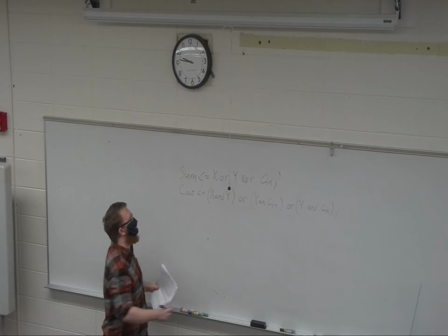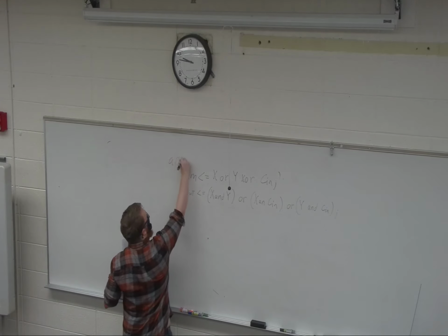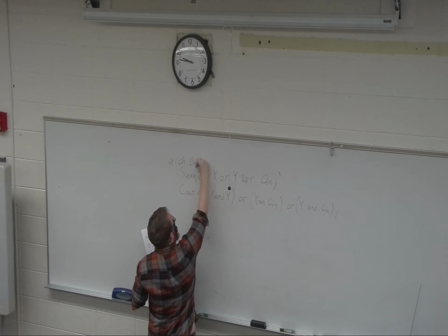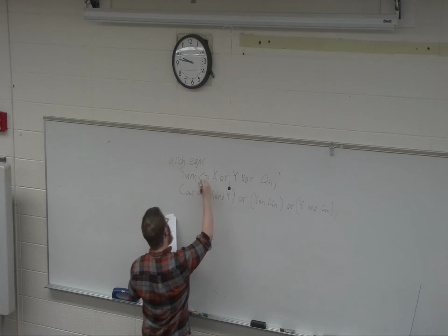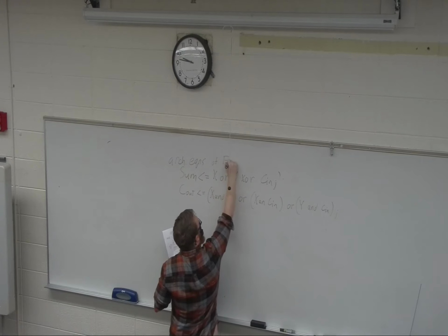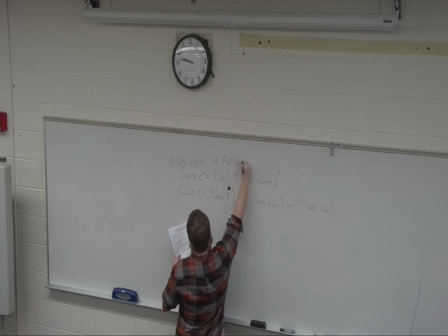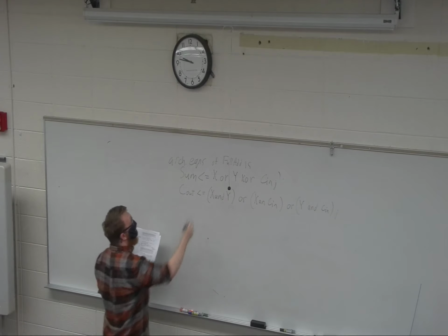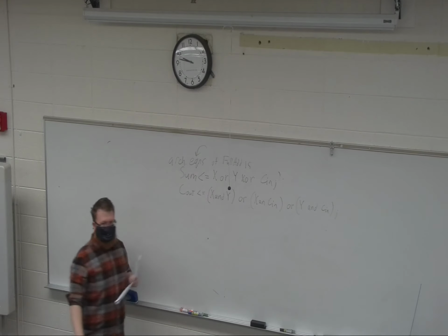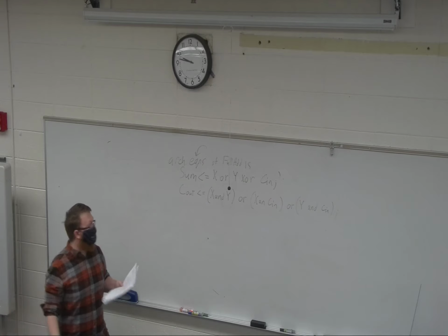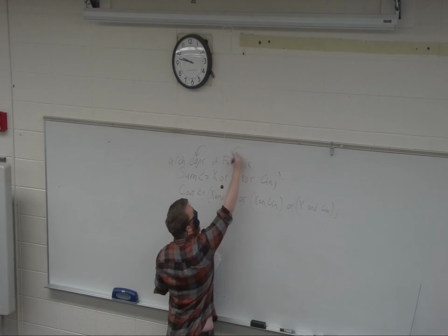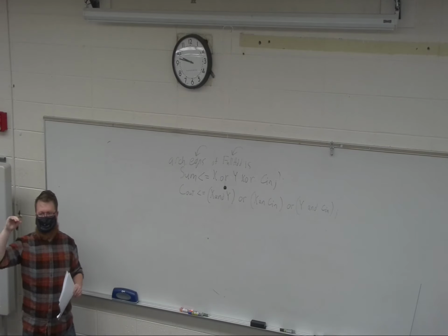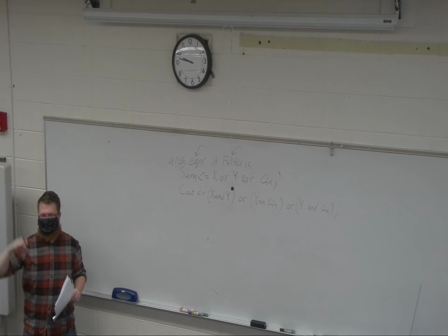When you write the architecture, I'm going to do some abbreviation. We're going to call this architecture equations of full add. The name is arbitrary. That's just you naming it something. The full adder, however, full add, needs to be the same as the top level entity, right? Because that's how you're making that association.